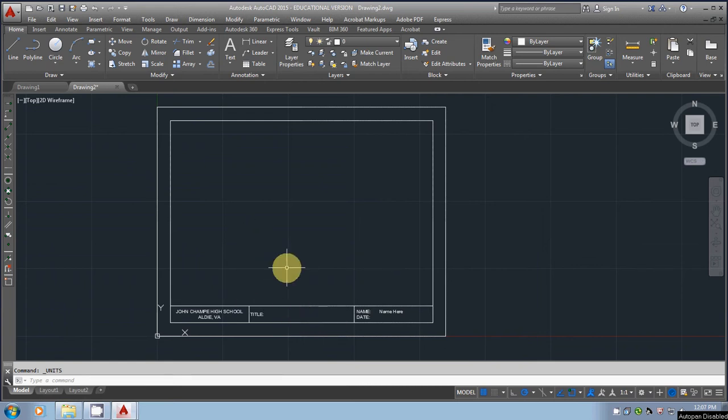The other thing I wanted to point out down here on this toolbar at the bottom corner of your screen, there's a couple things here that could be of use to us as we continue to look at CAD. And one would be the Ortho Mode. To use Ortho Mode, you'll check it on, and when you click to draw a line, it'll only draw it horizontally or vertically. Alright, it's not going to let us draw in any other angle. So if we're drawing really square parts or boxy parts, we can turn that off or on as we draw.